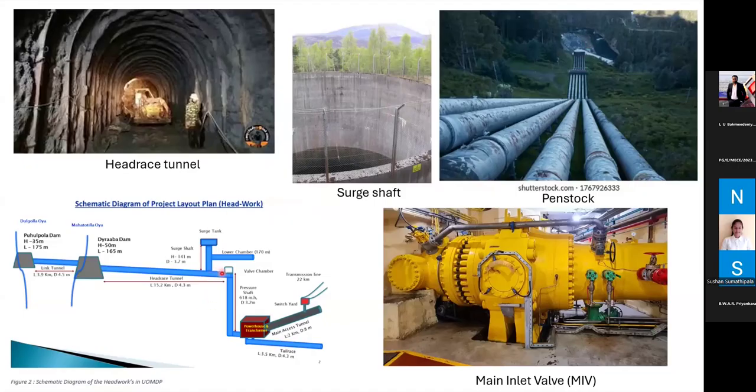The other aspect is that in the placement of the surge tank, if we can't directly place it at the end of the pressure shaft, the tunnel part should be realigned. This section should be realigned with metal lining, metal tubing, or the penstock itself to provide the necessary high pressure operational capability for the tunnel.